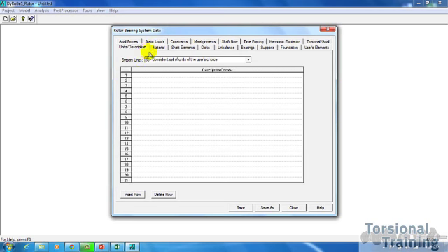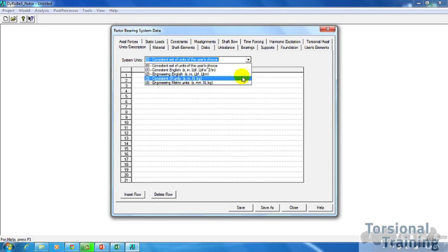So first thing I like to do is to set my units, and you can see Dyrobes has 4 different unit systems that we can use. One is the classic consistent English units, which is seconds, inches, pound force second square over inch. Engineering English, which is pound force and pound mass being the key differences, and then consistent SI units with meters and kilograms and newtons, and engineering metric units, which replaces meters with millimeters. So depending on what your preference is as far as units go, you can pick either of these options.